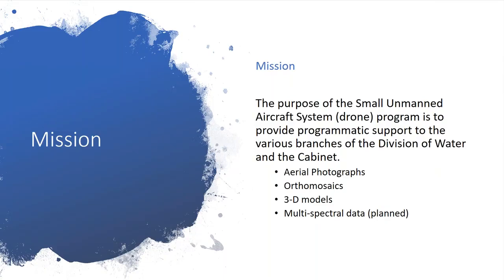We take those aerial photographs and we create orthomosaics out of them, which have GIS locational information built into them, so we can actually bring them into a mapping program. From that same information, we can build some 3D models and get an idea of how much material is needed to take out in a dam construction, for instance. We can figure out what the cut and fill volumes are in particular areas. Transportation uses these 3D models for building highways and that type of thing as well.